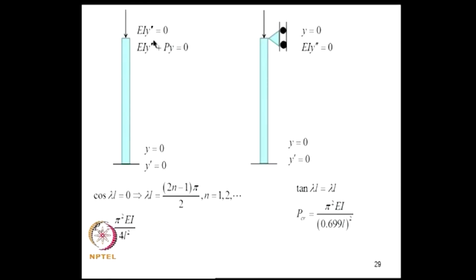Now, in one of the earlier lectures we have derived this, you can refer back, and towards the end of this lecture also we are going to see something about this. Now, the buckling mode shapes, like mode shapes in vibration, also have orthogonality properties that can be verified by considering a pair of eigen solutions, nth eigen function and kth eigen function. The nth eigen function will satisfy this equation, kth eigen function will satisfy this, Pn and Pk are the nth and kth eigen values.